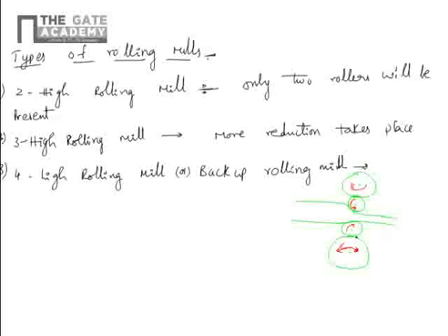This one's rotation is opposite. If it is rotating anti-clockwise, this one rotates clockwise. This is rotating anti-clockwise, this rotates clockwise. Power is given to the smaller rollers, not the bigger rollers, because the shaft won't withstand it. To avoid the shaft failure, this we use.